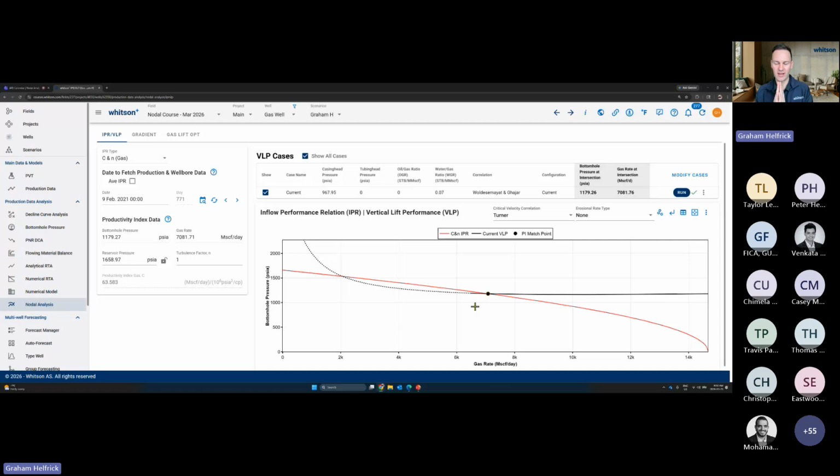So I want to talk about one thing quickly before we talk about different tubing scenarios, and that has to do with this sample point in the black line, right? This is the most recent day of rate and bottom hole flowing pressure. But often if your well is kind of going up and down, you might not pick a good rate. You might pick a rate that's not representative. It's too high, it's too low, and that can impact the shape of the IPR curve.